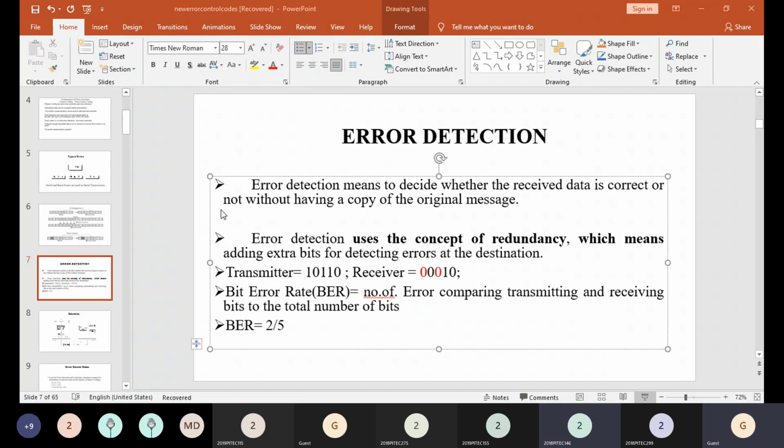K bits are taken as the input, and n bits are taken as the output. So the received vector R is nothing but the code word C plus the error vector. Depending upon the length of the code word, the error pattern will also change. Likewise, the generator matrix is G. Then you have the parity check matrix.